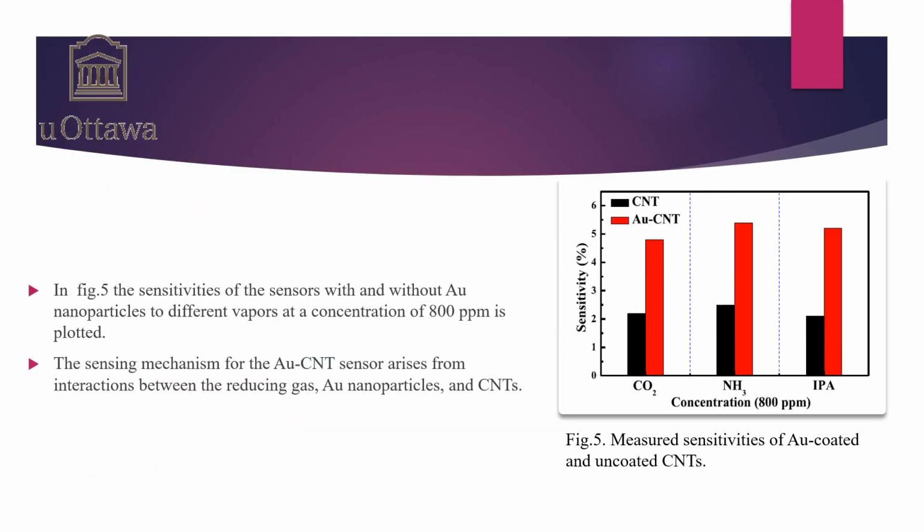Figure 5 plots the sensitivities of the sensors with and without Au nanoparticles to different vapors at a concentration of 800 ppm based on figure 4. All sensors coated with Au nanoparticles exhibited higher sensitivity than that of uncoated sensors.